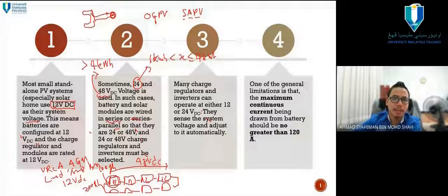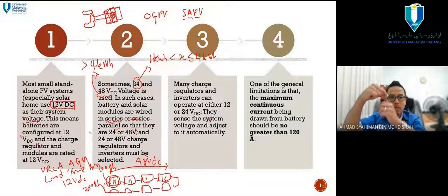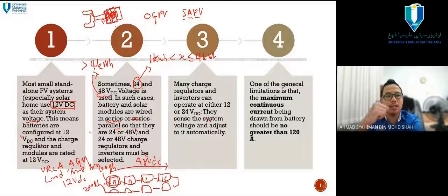Or if you don't have that kind of glove, then you use the black tape, the one people usually use for taping wires. If you strip the insulator of the cable and the raw copper wire shows, you wrap it with the black tape, so that when you touch it, it's not conductive. So while adjusting the bolt on top of the battery, the plus and minus.